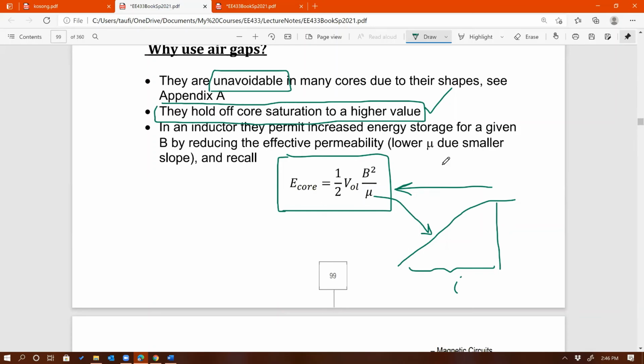Now, going back to this point, remember I said earlier about the flyback transformer needing an air gap. So we deliberately introduce an air gap. How do we do that? In the lab, I ask students to put Kapton tape between the two cores when they put them together. Instead of air, I ask them to put either paper or Kapton tape in between the two cores, right there.